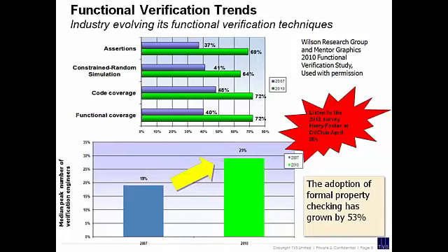Okay, so assertions. I'm asking you a question: what's the main advantage you would see from assertions? One of the things is to verify any particular requirement or a specification. Whether your code is actually doing that particular step or not. In assertions we tell you yes or no. So that would help us to find whether we are complying to the requirements or any specific action. Okay, so you can implement requirements as assertions to check the requirement, and you map that assertion back to that requirement. Okay, that's good. Sorry? You can debug faster.